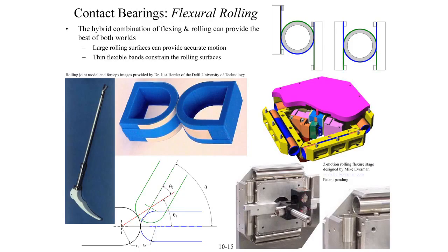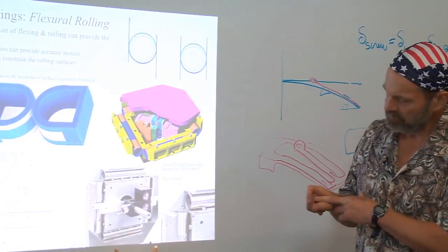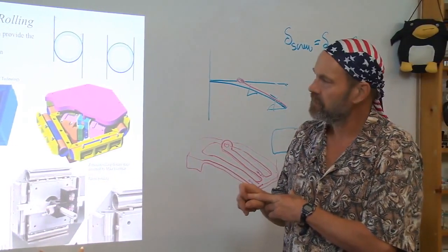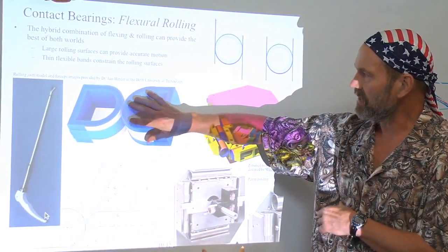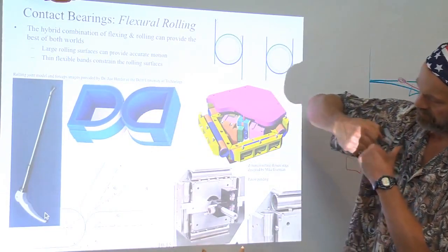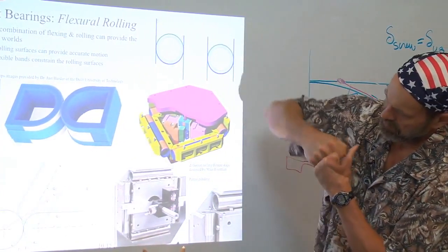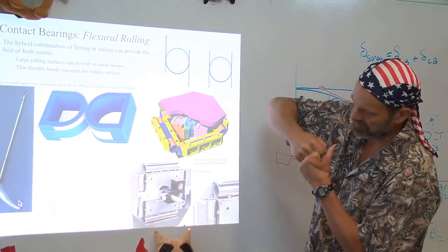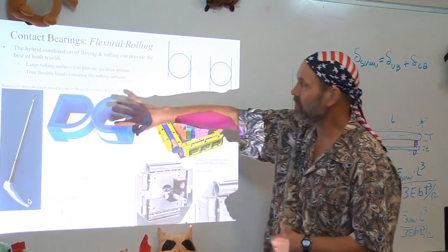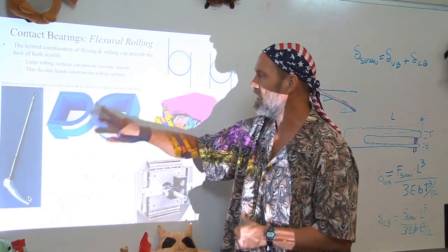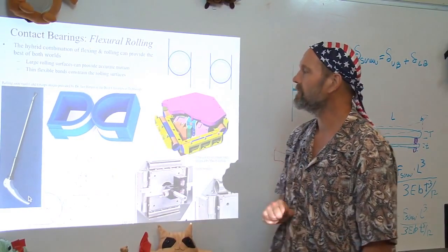Flexural bearings also have a very special place with respect to rolling motion, and indeed have been used for designing prosthetic replacement joints. Where they're used is if I have one surface that wants to roll over another, but you don't want the surfaces to come apart, you want to guide their rolling through a motion, even, for example, a cam-shaped motion, not necessarily round on round, but an irregular cam with another mating surface on it.